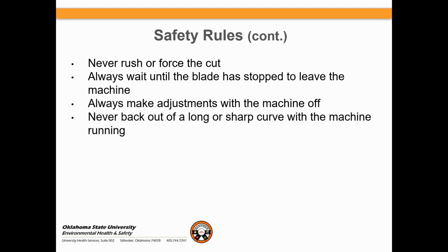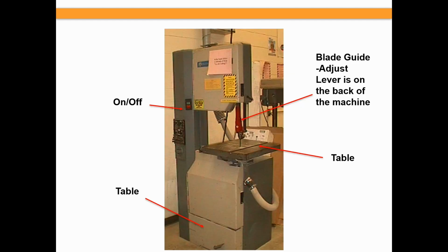Never rush or force the cut. Always wait until the blade has stopped to leave the machine. Always make sure that any adjustments are made with the machine off. Never back out of a long or even sharp cut with the machine running.